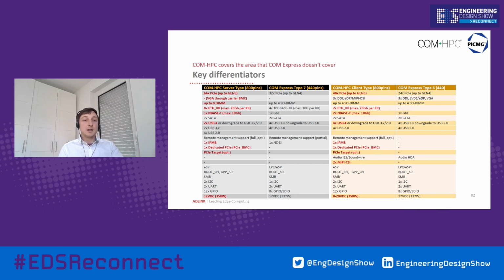And basically, what you've seen here is that some CPUs require more PCB space than is typically available on COM-Express, what you can see here. So basically the COM-HPC server module, so the CPU itself, is on the same footprint as the entire COM-Express module, right? So the standard itself defines more PCB space, and it allows higher electrical design power to get from the carrier to the module to really power these demanding CPUs.